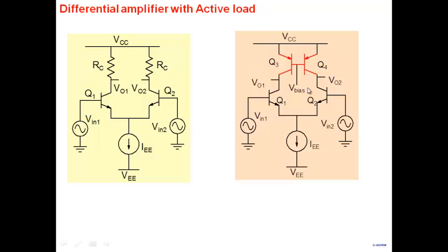Note that if, let's say, I apply 0.7, what is the net volt? Will 0.7 work? It will not work here, because the emitter base voltage, this is PNP, has to be close to 0.7 or so, to allow the transistor to conduct here. But note that the collector current of Q3 is exponentially dependent on the base emitter voltage here.